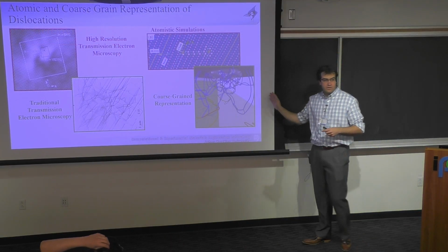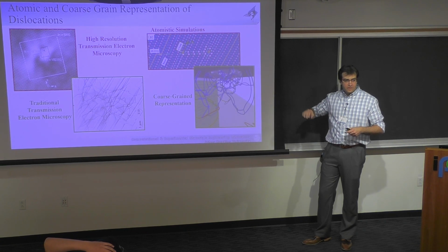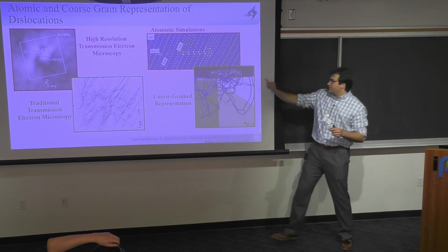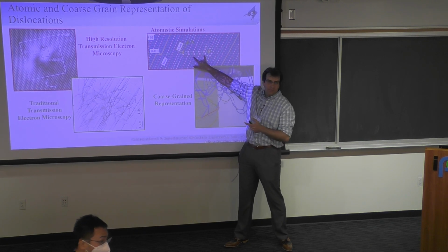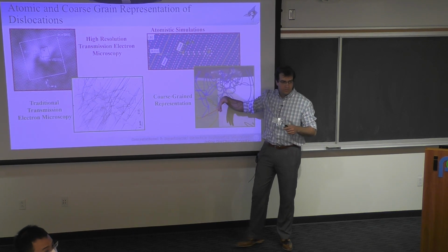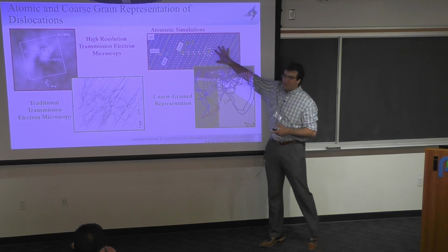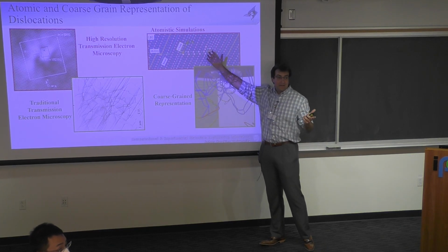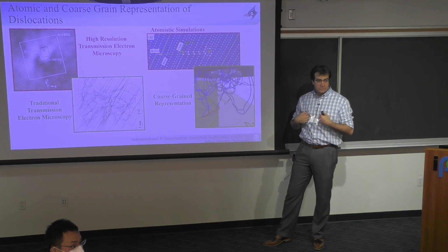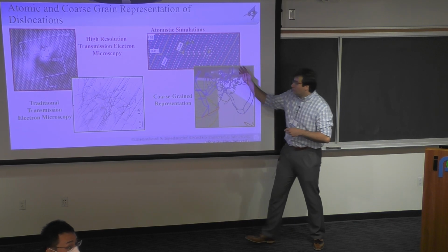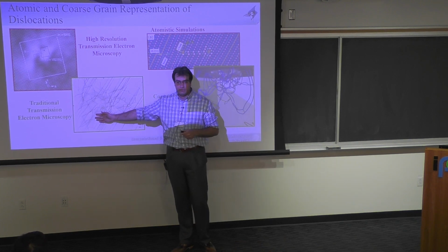This is DXA, which is part of Ovito, to extract the dislocation front. So you have two partials here, you can extract that, and you can identify what the stacking fault is, and so on and so forth. So it gives you a representation of coarse graining, right? You removed all the atoms that don't matter to me, and you only represented the defects themselves that I'm interested in.